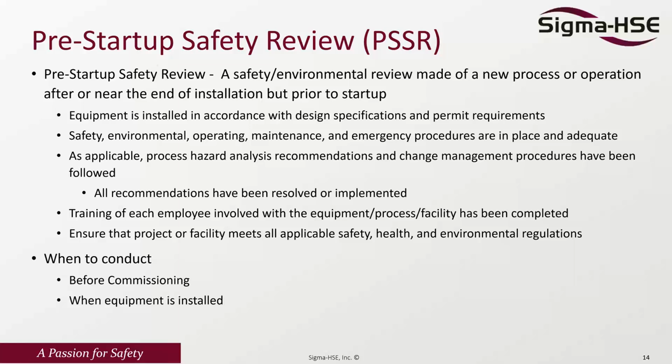And what we need to do is to ensure that the equipment is installed in accordance with design specifications, that the operating procedures are in place and the employees are trained. And very important is that the analysis from previous PHAs, being the preliminary risk assessment, basis of safety study, and the HAZOP, have been implemented or resolved.